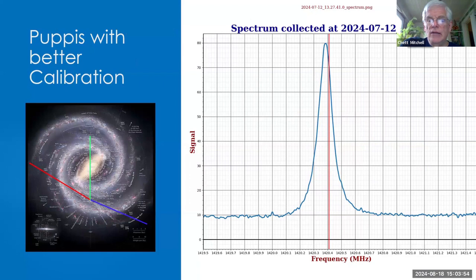The thing that I had to learn about calibration is that the procedure involves pointing the horn straight up for the cold calibration and then at the ground for the warm calibration. And I was treating my telescope as if it were a digital camera. So I would point it up, leave it pointing up for 10 or 15 seconds, and then point it to the ground and leave it 10 or 15 seconds.